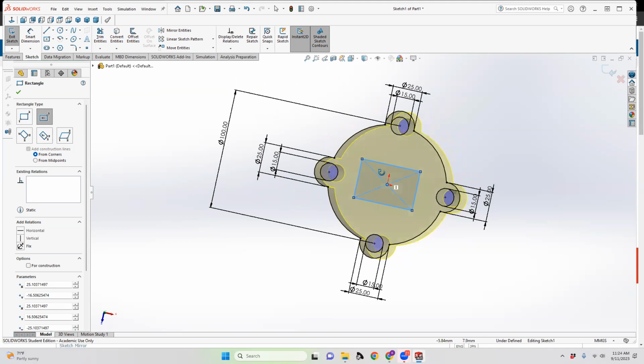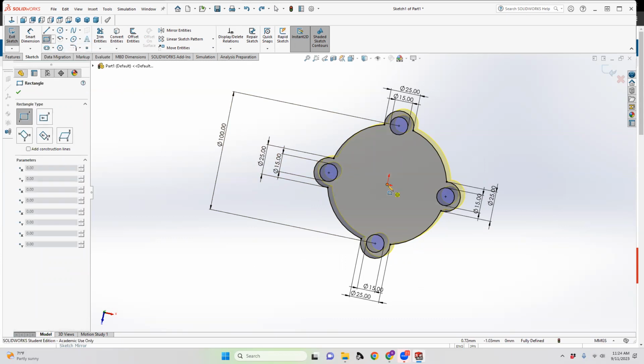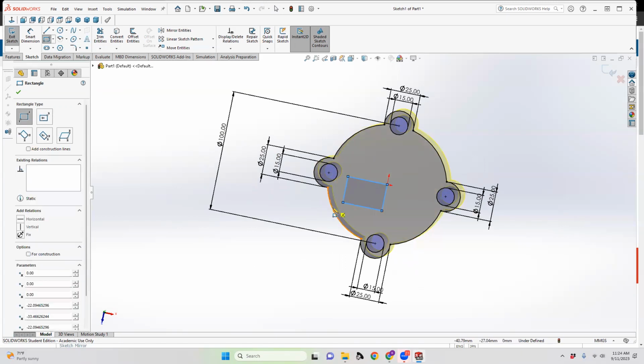Center point rectangle, you're going to have a little better aim, but if that was an edge or corner rectangle, you might think that this is giving you a big distance here, but actually, when you see here, this may be a different dimension than what you thought. So it gets to be really cantankerous to try and do things at weird angles.